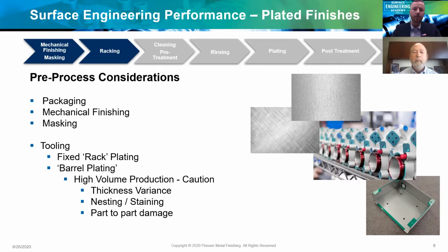but really limited to a smaller envelope and type of parts, parts that don't have blind holes or deep recesses, or even flat parts that lend themselves to nesting or, of course, part-to-part damage with heavier parts and sharp edges. So want to be cautious there. Of course, barrel plating versus rack plating is going to be apples to oranges with price. So if you're after a very cosmetic finish, a consistent finish, consistent thicknesses, you're going to want to consider rack plating versus barrel. Doesn't mean you're dead in the water with barrel plating, but certainly more risk involved there.